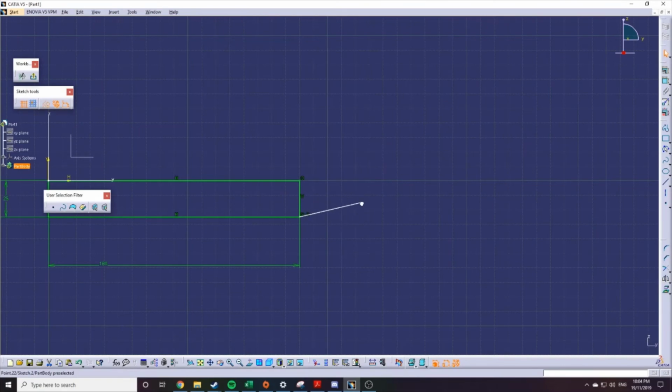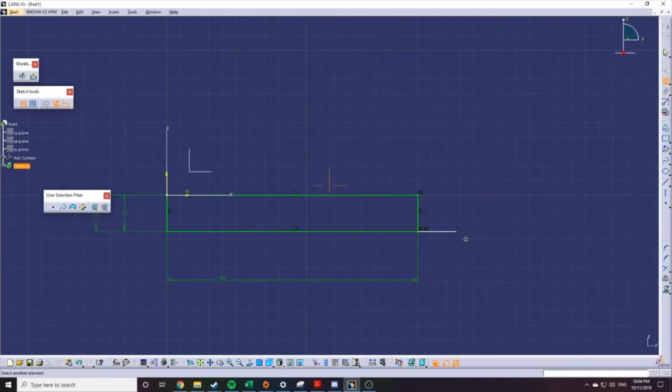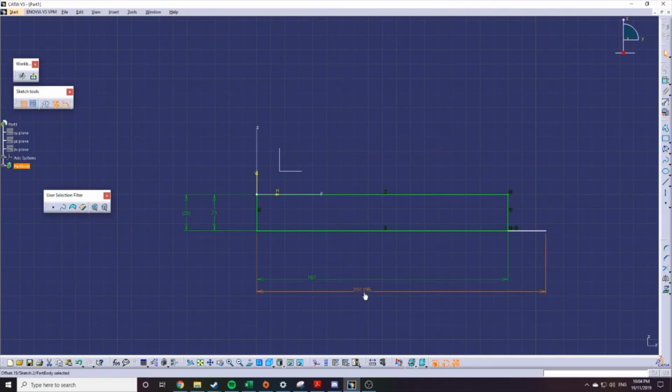And say we want that to just extend out to maybe 210, which is the maximum length of an F1 in Schools CATIA car. Easy. So now we can only change the angle. So we can define an angle by going like this, selecting the line you want, and then selecting another line that you want to angle it between. This will give you angles. In this case, I want this to be horizontal. So I can then go back to this box and then just click horizontal, which will do the same thing.